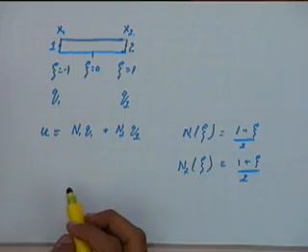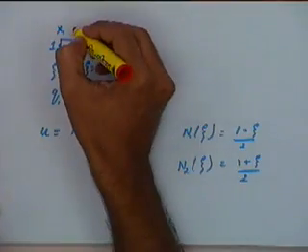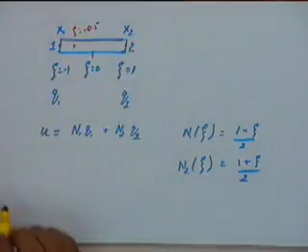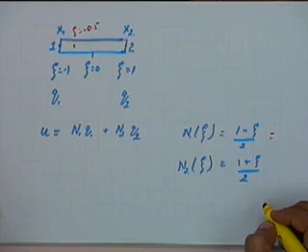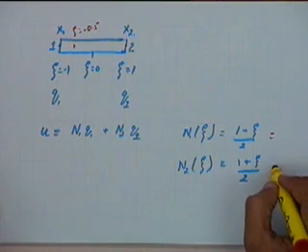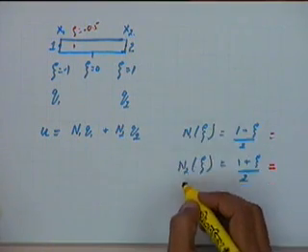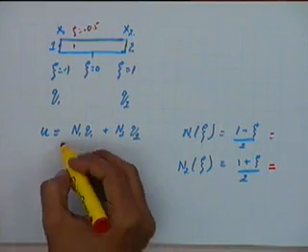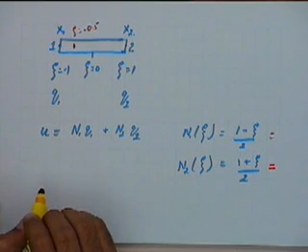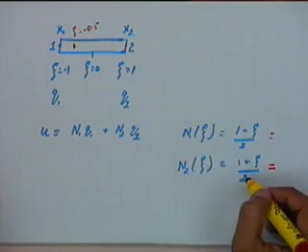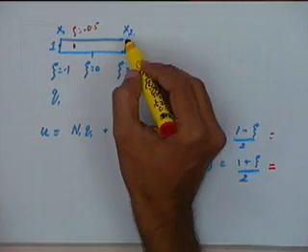What we are basically saying is that if I take any point inside this element, let us say a point where zeta is equal to minus 0.5, I will get some value of n1. Similarly, if I put zeta equal to minus 0.5 in n2, I will get some value of n2. For these values of n1 and n2, I can put them here and I will get some value for u, that will be the u at this point. And since n1 and n2 vary linearly, this relationship gives a linear variation of u along the length of the element.